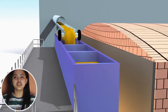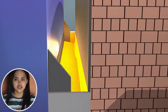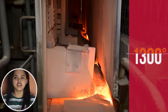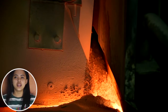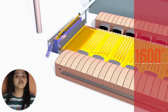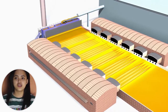The batch charger regularly lays down raw materials at the furnace entrance on a part of the line called the doghouse. The raw materials drop on the 1300 degrees Celsius molten glass already contained in the area and are continuously pushed inside. In the melting zone, the batch of mixed raw materials melts at a temperature of 1550 to 1600 degrees Celsius until it becomes liquid and merged.